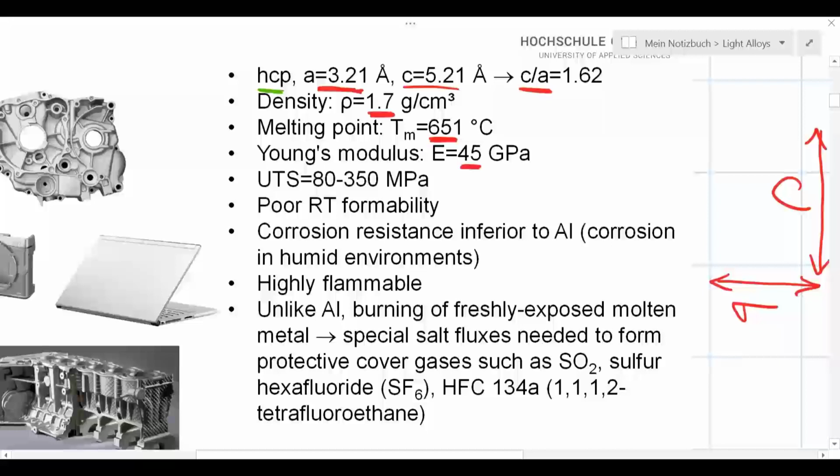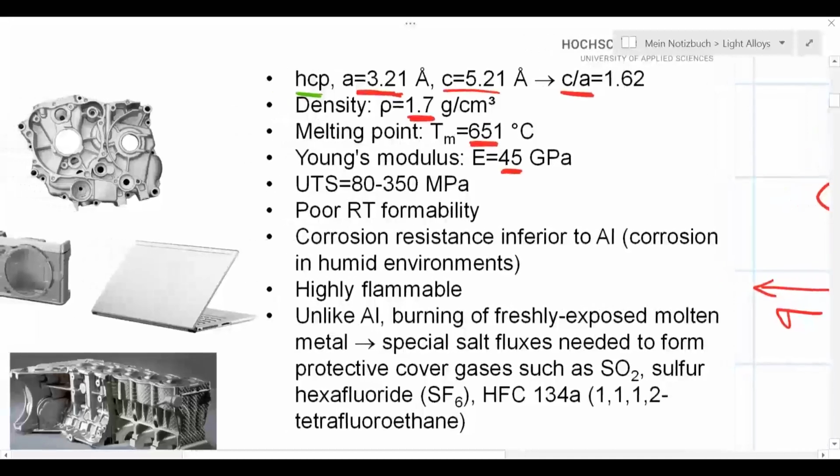We could use tools out of steels in order to process aluminum alloys. If you want to make a mold in order to cast magnesium, we could think of a metallic mold out of steel. So we don't have to go necessarily to ceramics. Indeed, magnesium alloys are also cast in ceramic, in sand molds, but we got the option to use steels.